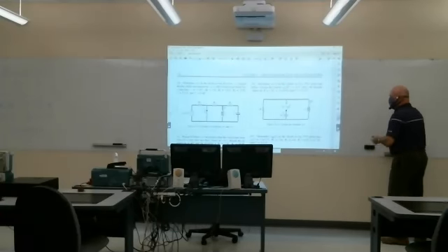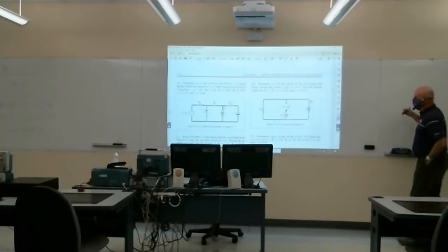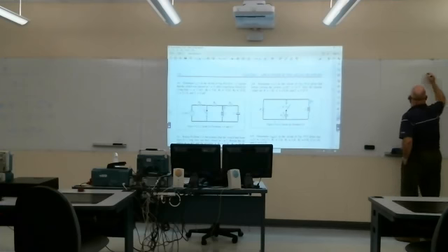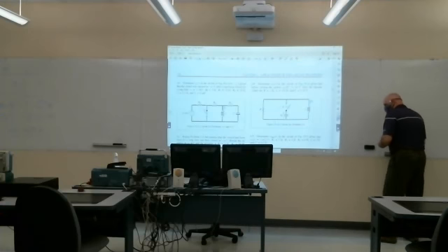Here you would only have the zero input response. So determine the current through the inductor given before the closing of the switch. The capacitor is charged at 24 volts. But we're looking at after the switch is closed.